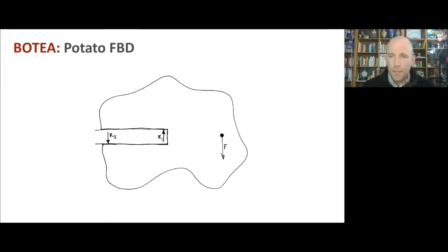And it's a very common sort of equilibrium problem that we will run into over and over again in these kinds of systems, such that the longer this lever arm is, the smaller this reaction force needs to be in order to react out the moment caused by that force. And oftentimes, a smaller force is beneficial.